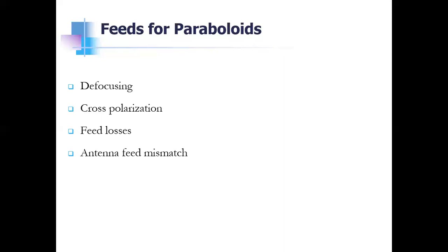There would be impedance mismatch at the feed because some of the energy is reflected back by the antenna surface, and this energy re-enters the feed and the transmission lines connected to the feed. This brings impedance mismatch between the antenna and the feed. This is also not desirable, so we have to check for this.